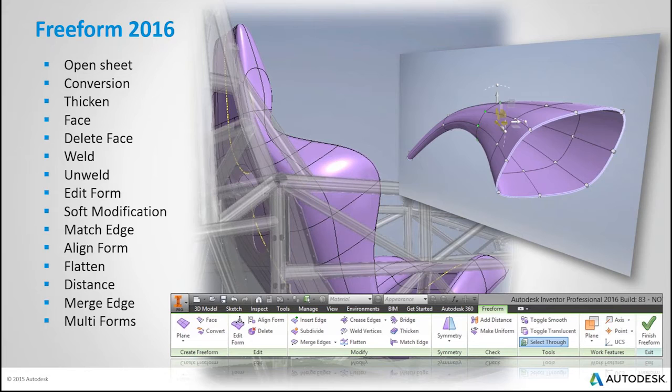You've got conversion, thicken, face, delete face, weld, unweld, edit form, soft modification, match edges, align form, flatten, distance, merge edge, and multi-forms. One I think is quite important to mention here is match edges. What you can do is you can do a 2D sketch on a work plane, and then you can match the edge of your freeform to that sketched profile, so it ties up to a known surface. So it's not all just about pulling it and pushing it. You can actually do it fairly accurately as well to make sure it fits in the criteria that meets your needs.